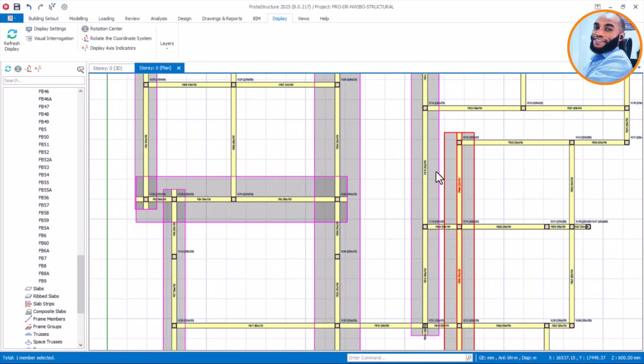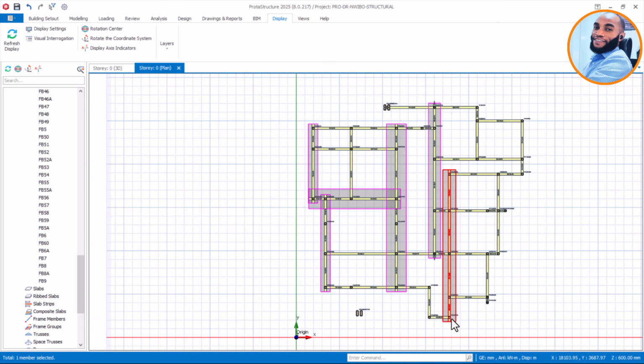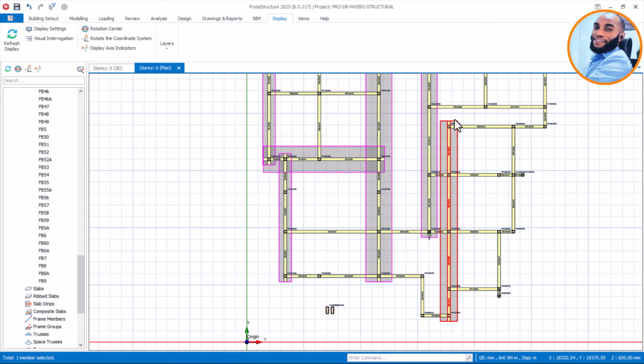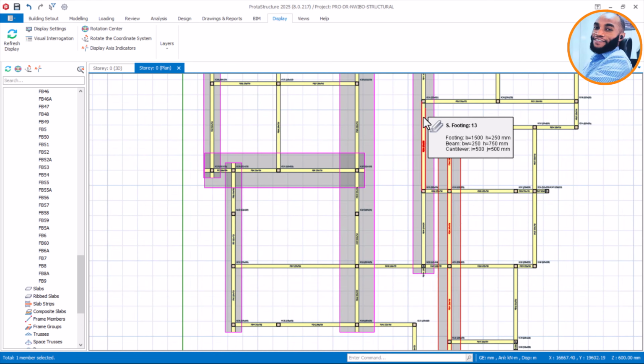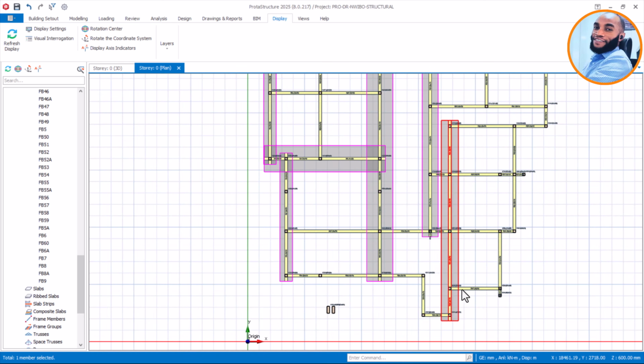Okay, that is fine. Now had it been clashing, then you would have to choose either to look at this line of wall. If it's a major wall that you cannot ignore, then you can change the choice of foundation, because if there is a clash, you can either choose to ignore that wall line and use only one wall line, or you change the choice of foundation.